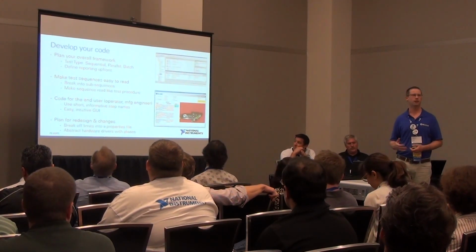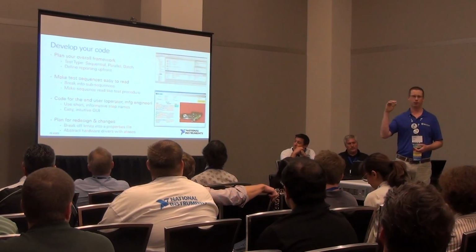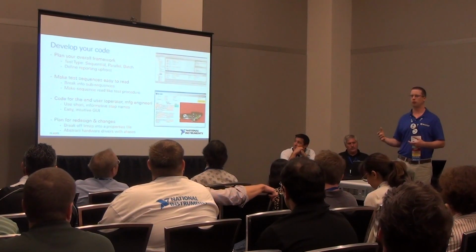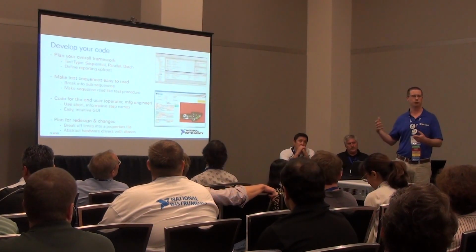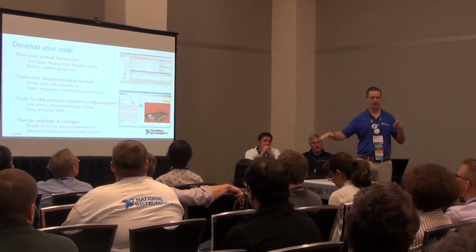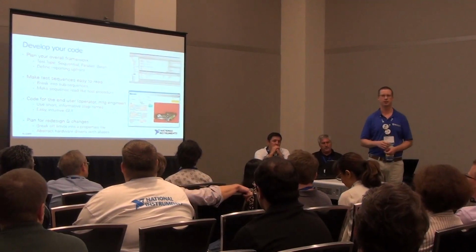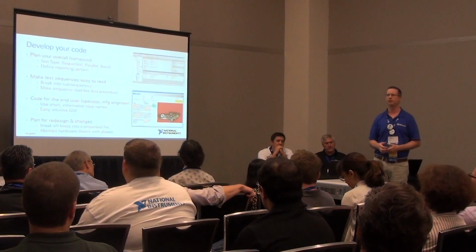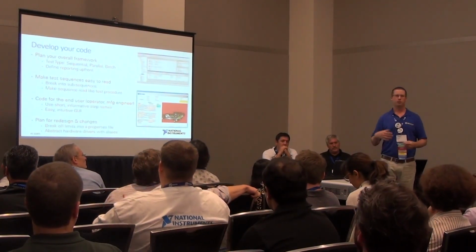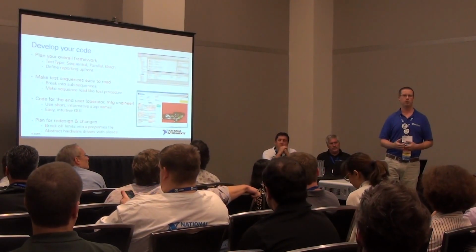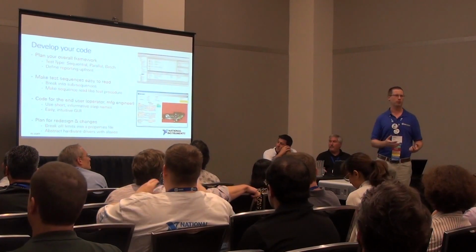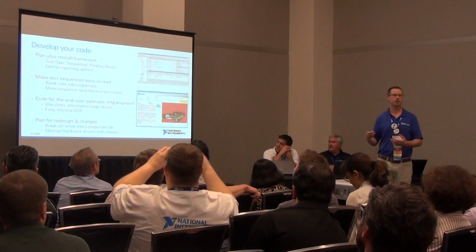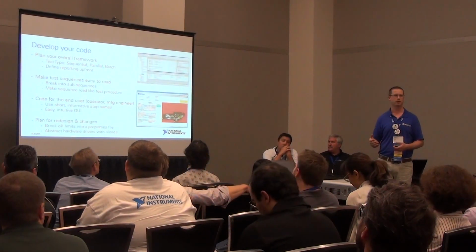Are you running a single-up test, sequential, run product after product after product? Or are you doing something that's more multi-up? You could do a parallel model where you have individual UUTs being tested asynchronously, or a batch model where everything runs from the top down to the bottom and starts and finishes at the same time. Oftentimes you'll need to configure your reporting, so your different departments may have different reporting requirements. By defining that up front, you'll understand what your end goal is and be better able to serve your customers.